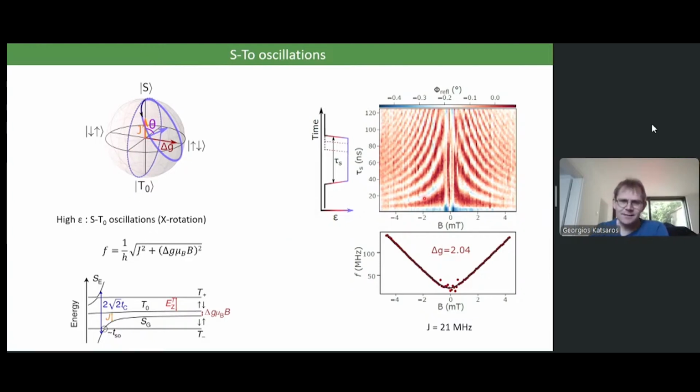A very interesting thing, what we observed is that actually the G factor difference between the dots is 2, which is a very large value. When you do this experiment with silicon, the difference in delta G is actually 2 times 10 to the minus 3. So due to the fact that we work with holes, the G factor difference is very much enhanced, and that's why actually we can operate our spin qubits at such low magnetic fields.